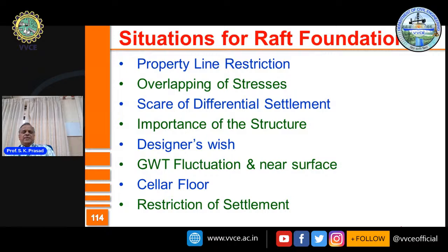I think it is time for us to stop because I need to tell you, today we solved a number of problems related to terminologies of bearing capacity theory. And then we moved to the higher order bearing capacity theory. So Meyerhof's bearing capacity theory, I explained to you. Likewise, you can take Vesic's theory, you can take Bowles' theory, doesn't matter. They consider more factors into account. So we then talked about the one given by Meyerhof.